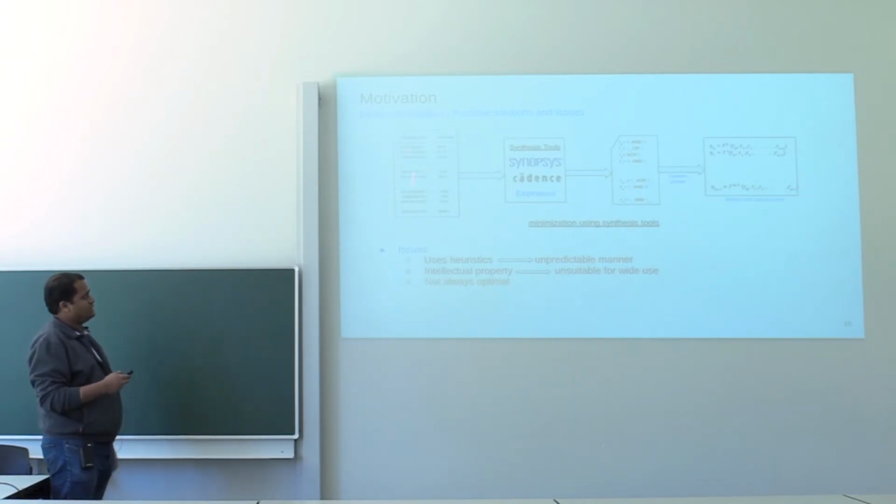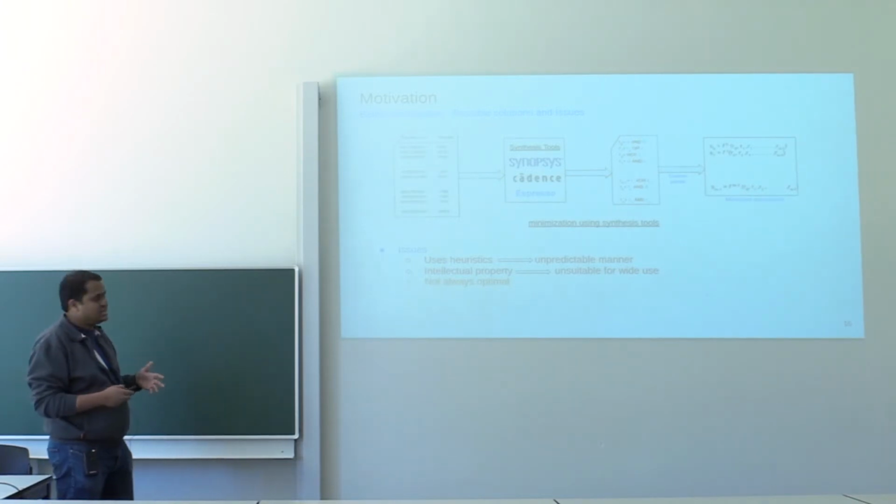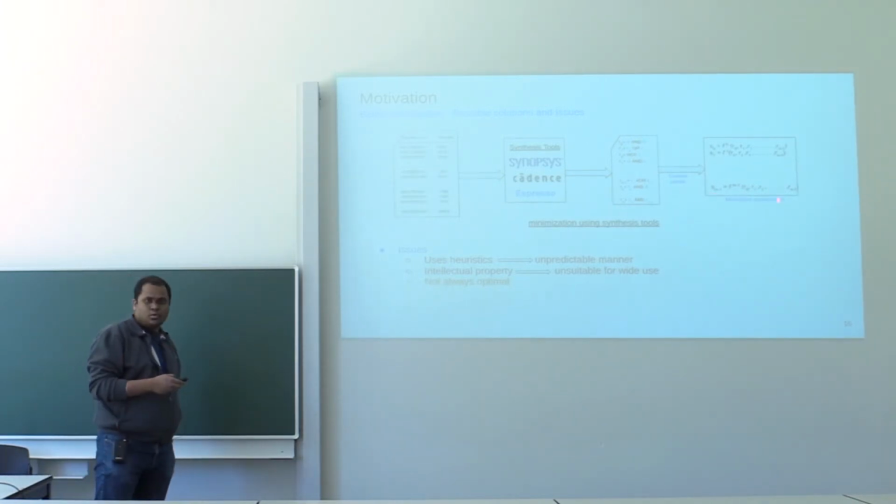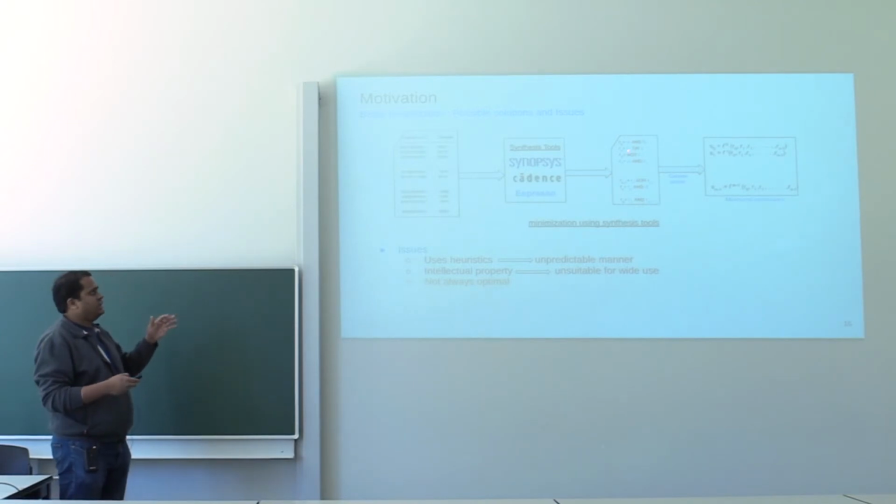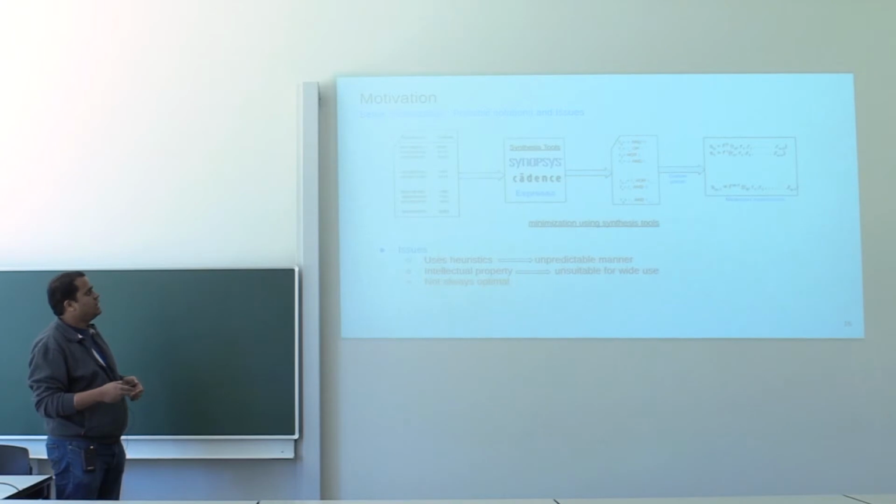We have this long list of random bits and their corresponding samples. We put them in a file and give them as input to some synthesis tools, and they generate some values in their internal representation. From there, we can write our own custom parser that can read these internal files of the software, and then generate or minimize expressions.